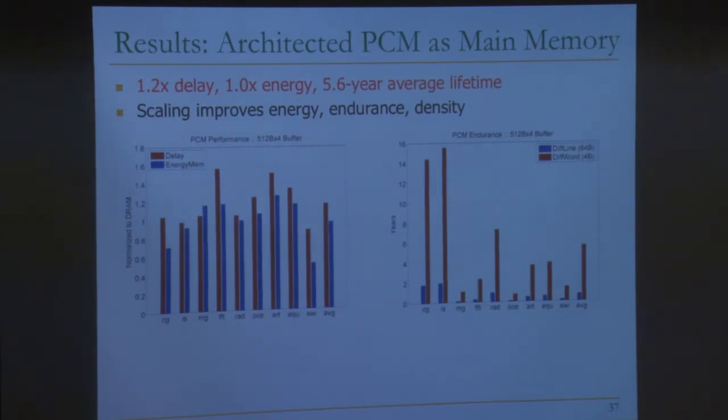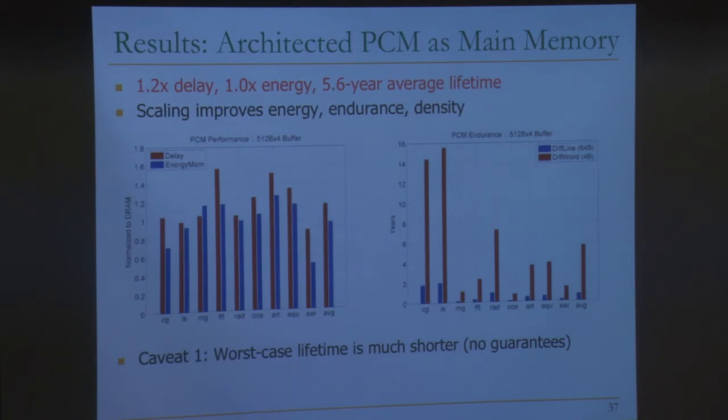And we talked about this before, but PCM is expected to scale more and more and more. And all of these benefits, guess what? They get even better when you start scaling the device. So that's great. A couple of caveats here. One, if you have a worst case access pattern, let's say you know the device layout, you know the wear leveling algorithms, you know everything that's going on in the system, you could come up with an attack that actually exploits this system and causes a really, really short lifetime once again.